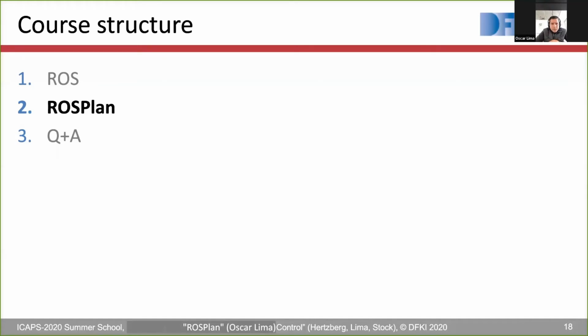Yeah, so another question: in what cases do we want to use client-server messaging instead of using topics? Actually, the client-server architecture, so these are ROS services and ActionLib, under the hood are actually using topics. If you want to request a service from a node, you could implement your own service just using topics. You make one topic with the message, with the parameters that the service requires to work, and then you publish this message on a topic.